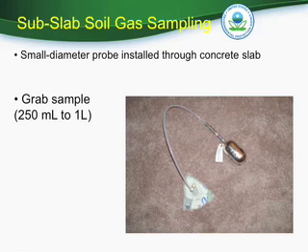And then in a lot of commercial buildings, they may have equipment rooms where they have direct access to the subsurface. And so these kinds of conduits or things that are actually cut through the slab, these can be utility conduits and things like that. That might be a place where we're taking what we call a pathway sample, and we typically find higher VOC concentrations there.